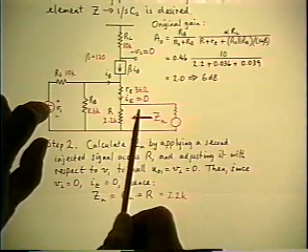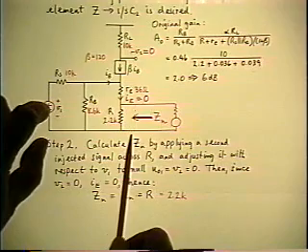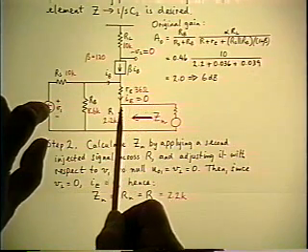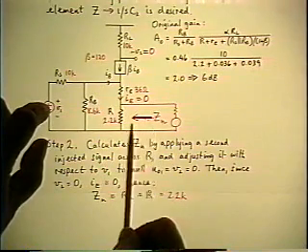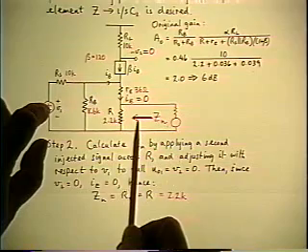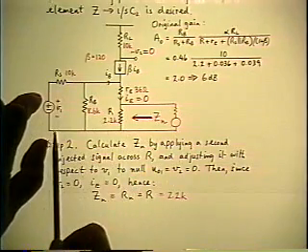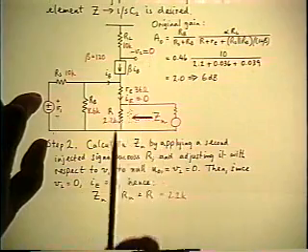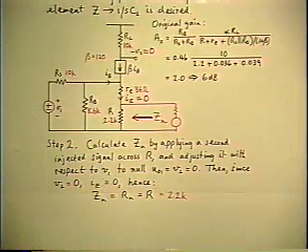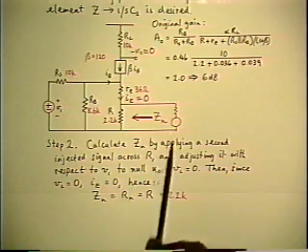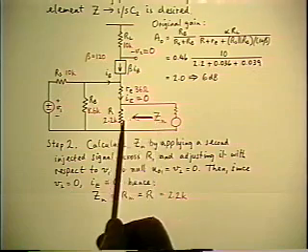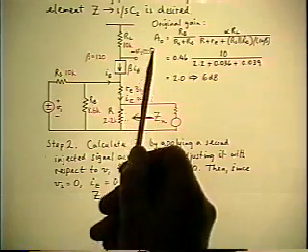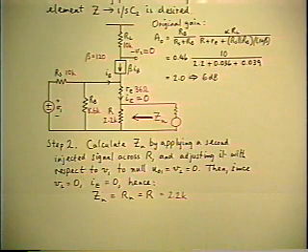Then you take a pair of meters and you measure the voltage across the second source and you measure the current that goes in. And that ratio, by definition, is Zn, the driving point impedance seen by the second source in the presence of the hidden first source, which is adjusted to null the other output. So that's the hardware implementation. Analytically, all you have to do is calculate this impedance looking in under the condition of nulled output. This is the only new thing conceptually you have to do.